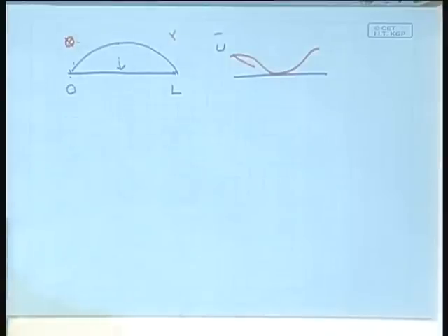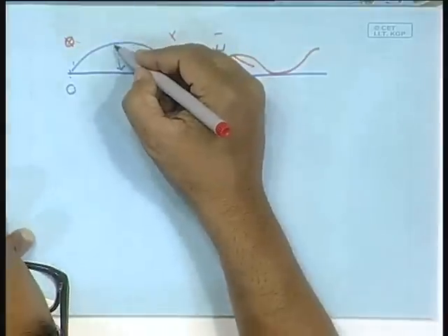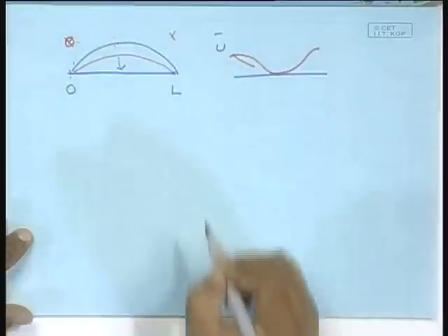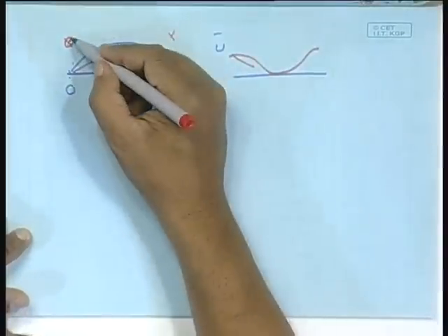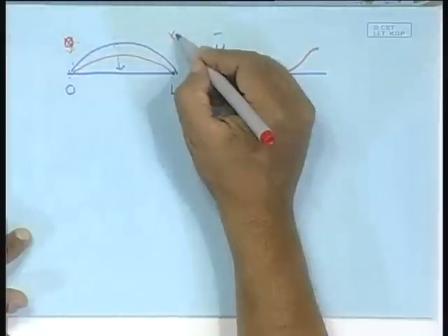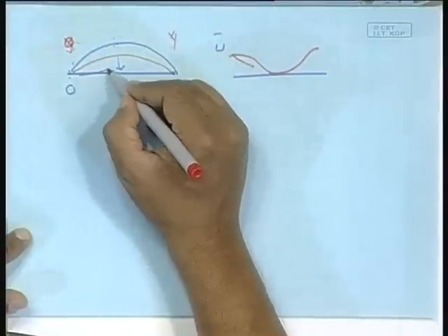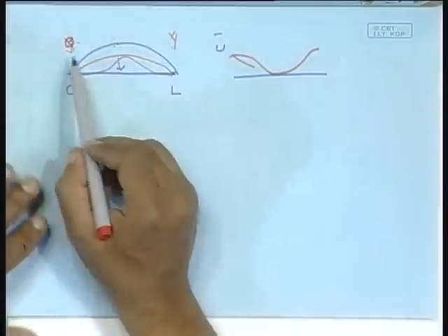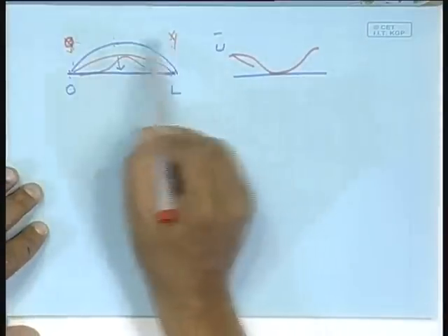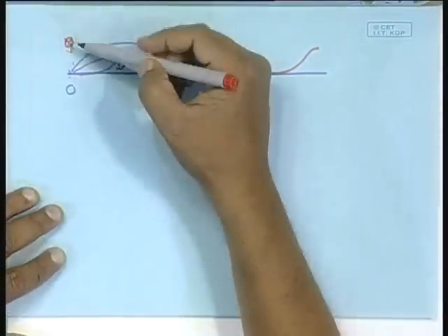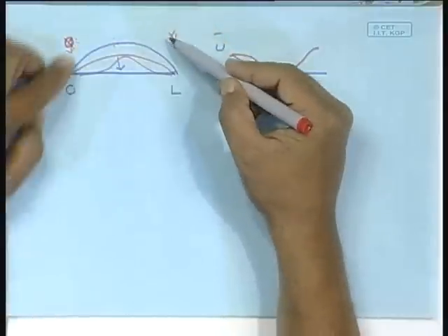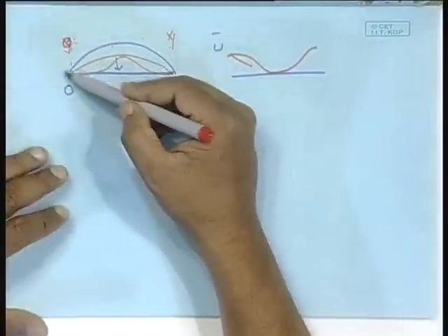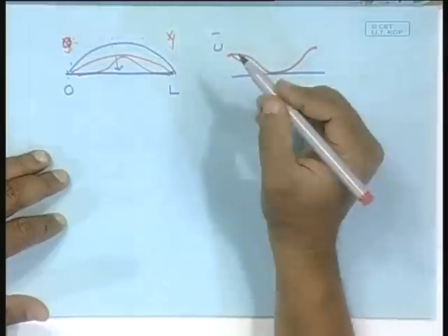Now, as time evolves, the deformation goes down. So, at a later time the deformation will have gone down. The potential energy also would have gone down. The kinetic energy would have picked up. So, the energy has been converted from potential to kinetic energy, and some of the energy flows in from the two nodes, and it is now distributed along the entire rod.